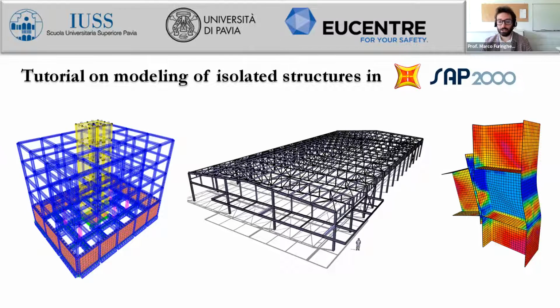But maybe it is just because you first solve the modal analysis of the structure, and so you have all the vibration modes of the overall structure. In my case, it was a steel frame, and then the software has just to compute the modal functions, which are numerical functions which multiply the deformed shapes of each mode, so that this is very much faster, because it uses an already performed analysis, which is the modal one.